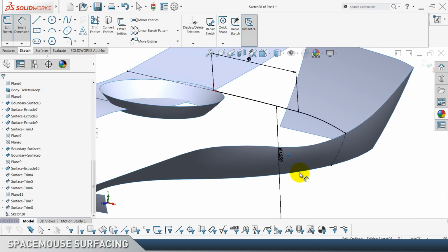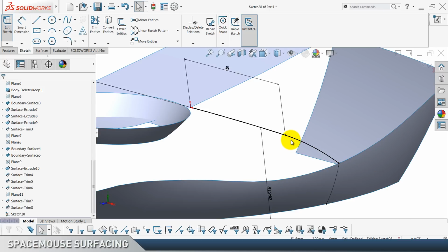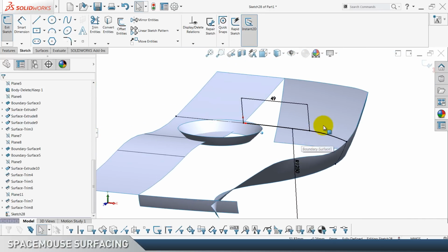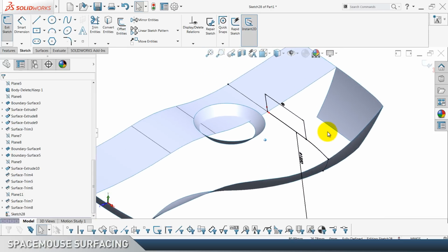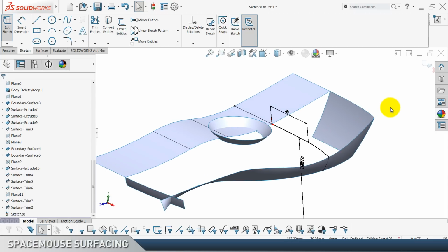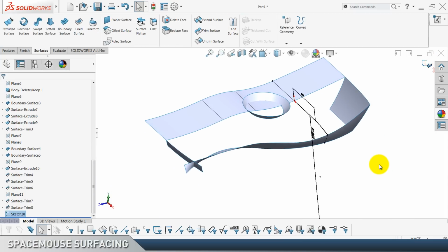Again, that's something which is gonna fully define the sketch, and as you can see, these two edges are pretty much gonna follow each other and define that shape we are gonna build. So exit the sketch, let's see what's next.